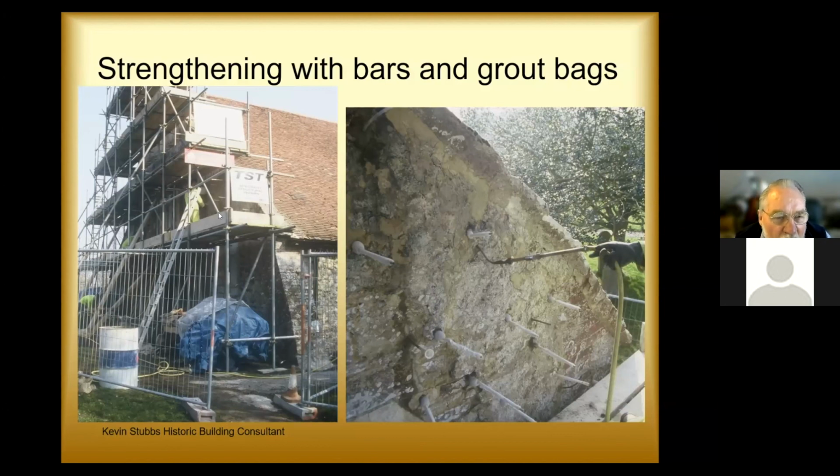8-meter long drills right through the structure and put anchoring rods in, and those rods are perforated, they're hollow and perforated. Around those rods you put a fabric sock, and then you pump grout into that hollow rod, and out through this coarsely woven fabric sock, you get fingers of grout moving out and filling the voids within the structure.